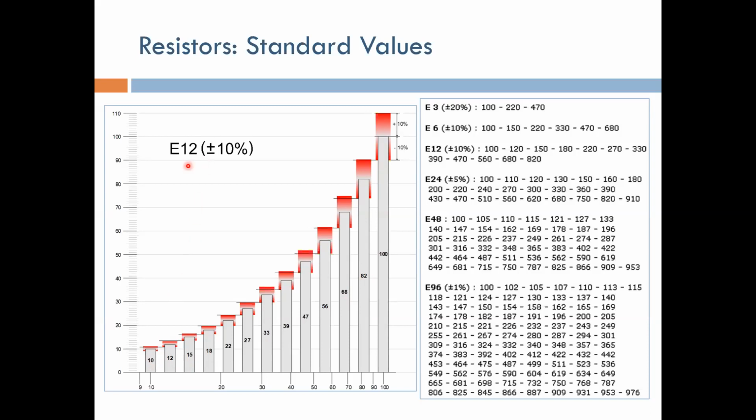The idea behind this is the plus minus 10%. If you take the value of the resistance and put it at plus minus 10%, the values are designed such that each resistance has a range that minimally overlaps with the range of the other resistances. As you see here, the plus minus 10% from the 82 has very minimal overlap with the plus minus 10% from the 68, and so on and so forth.